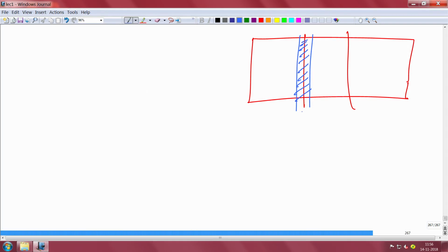This is a very tiny depletion region, but essentially the delay with the base emitter junction will be given by the capacitance associated with it, which is CBE, times your resistance, that is the RC delay, if you recall, okay. And what is the resistance that you associate with that? This is emitter, this is base.